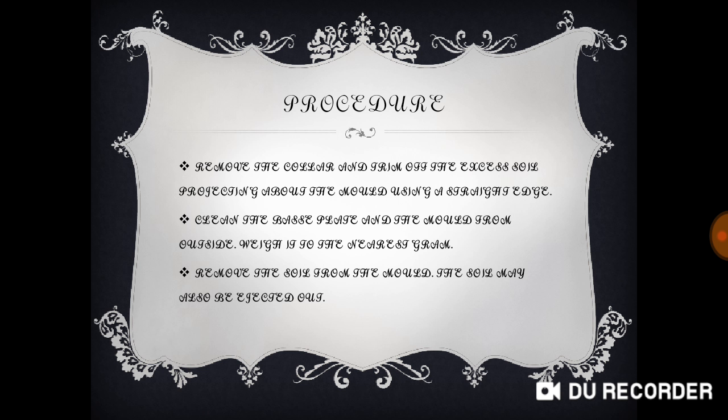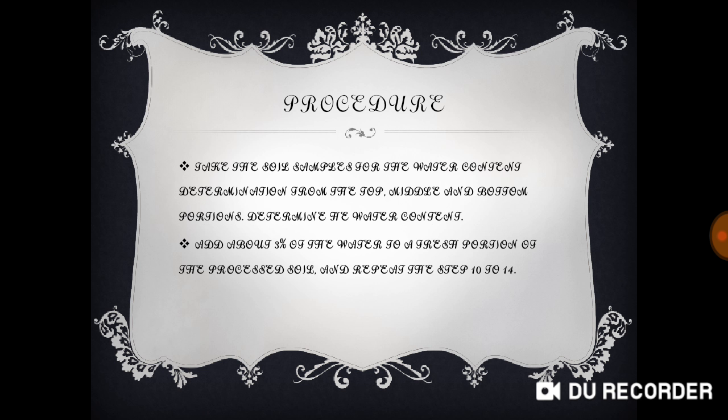Remove the soil from the mold. The soil may also be ejected out. Take soil samples for water content determination from the top, middle, and bottom portions. Determine the water content. And lastly, add about 3% of water to a fresh portion of the processed soil and repeat steps 10 to 14.